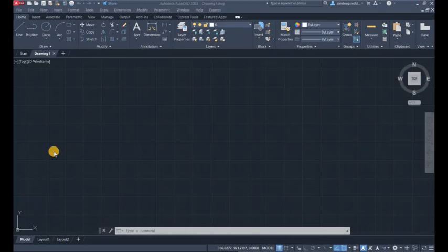We'll also come across polyline. Polyline is just to the right of the line command or the line button. Poly means many, so a polyline has many lines which are joined together. If you create an object using polylines, you'll end up with a 2D solid, and then you extrude the 2D solid to get a 3D solid. The difference is, if you draw an object using lines, AutoCAD will treat it as lines. Then you cover how to extrude it. It's very, very simple.